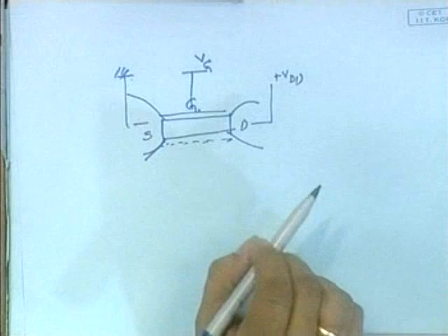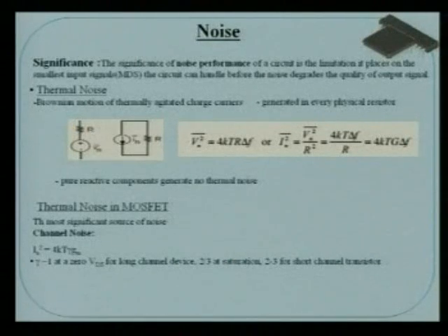Then you can use the MOSFET transistor noise, the channel noise, because of saturation, because of thermal noise, which is 4kTγgm, where gamma is a parameter; when VDS equals 0, gamma equals 1. And for a long channel device, what do I mean by a long channel device? When the dimension is 2 micron, 3 micron or 1 micron.